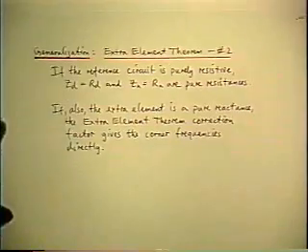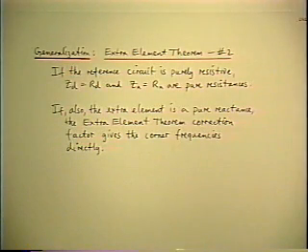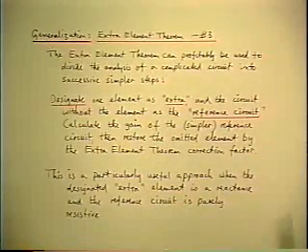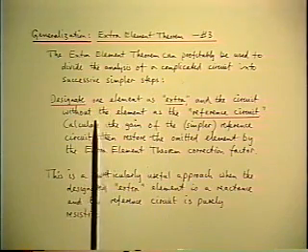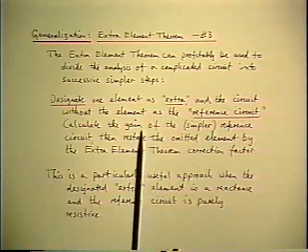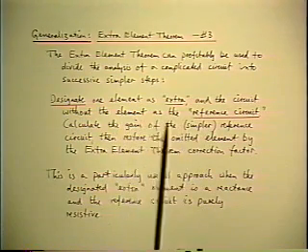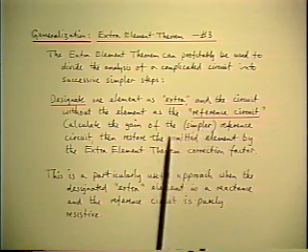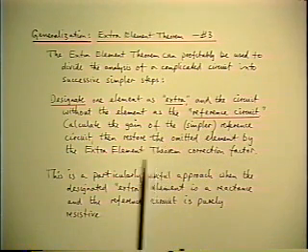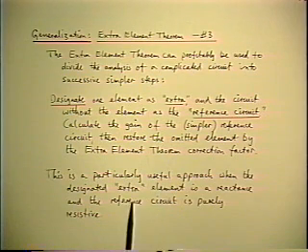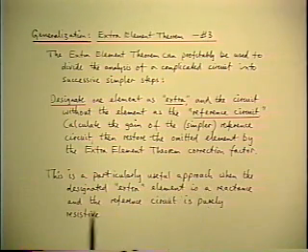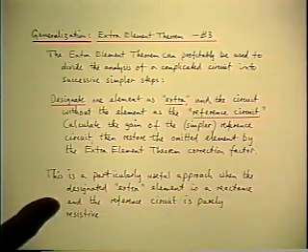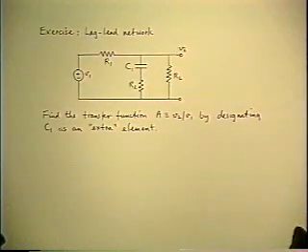So there's the generalization I just talked about. And here's the other class of useful applications. Even if you know everything that's there already, designate one element as extra, and the circuit without that element becomes the reference circuit. Calculate the property of the reference circuit, and then put the element back in. And this is particularly useful and simple when the designated extra element is a reactance and the reference circuit is purely resistive. Let's look at an application of that.